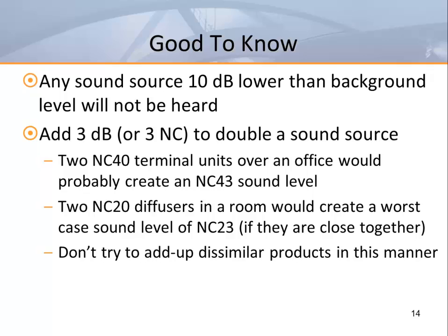So we come away with 2 good things to know. When there's a difference of 10 or more decibels between sound sources, they're no longer additive. Whenever you want to know the effect of doubling sound sources, just add 3 dB or roughly 3 NC.